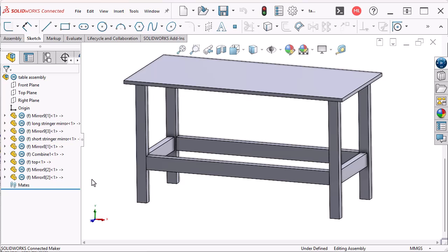And I believe that this method is easier to control. You've got fewer in-context relationships. This still has the external relationship symbol, but that's because the individual bodies from one part were published to another. It isn't an in-context relationship where one part is related to another part through the intermediary of an assembly.